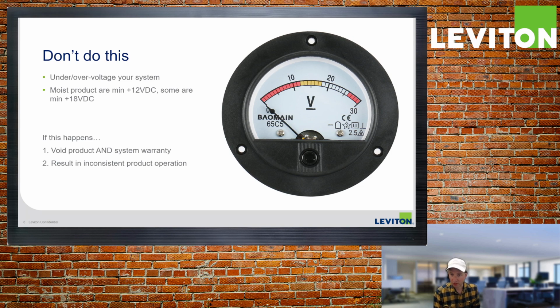If you do over or under voltage your system, it will void the product and system warranty, and it could result in inconsistent product operation. Now, one of the things you will note, and I'll mention this in just a couple of slides, is that as voltage goes down, current draw goes up. So by not planning correctly, you can accidentally over voltage your system or over current your system, because at 12 volts, the current requirement is twice what it is at 24 volts. So these are very big issues. Again, I'm going to show you some really quick ways to make sure you don't have problems.